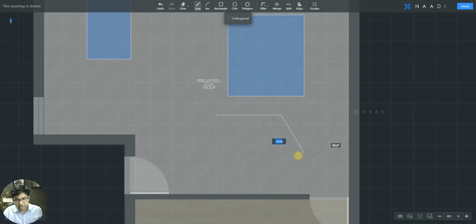Okay, don't worry, the previous typed in dimension will be locked. So now I can type in as 1 meter here, press enter. Now we precisely created another line which is 1 meter in length and at an obtuse angle of 60 degree. Now I can do the same process here.